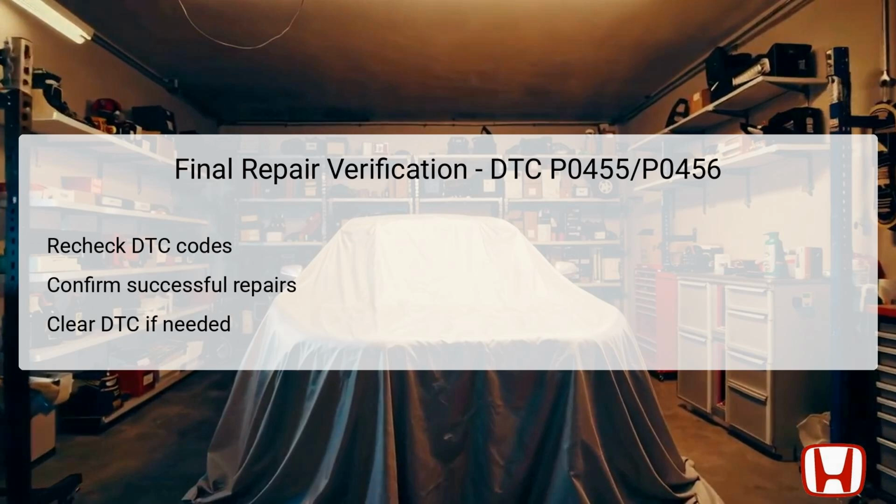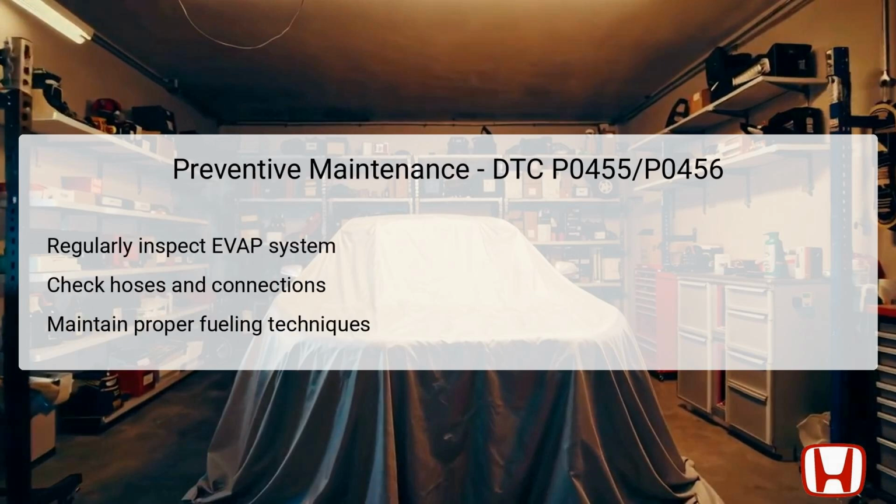To avoid encountering DTC P0455 and P0456 issues in the future, preventive maintenance is key. Regularly inspecting the EVAP system and its components, such as hoses, valves, and the canister, can prevent leaks from developing.